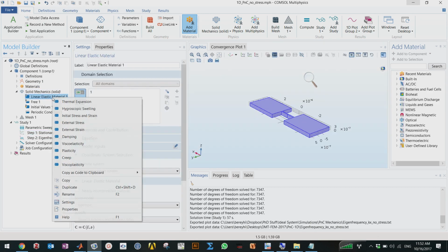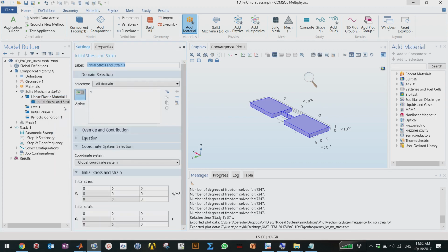All right. So here I come back, I see the initial stress in X and Y is defined. There is one more boundary condition that you need to add, which is a fixed boundary condition. So you want your ends to be fixed, and then release your structure, because if it's all free, there is no point in relaxing.